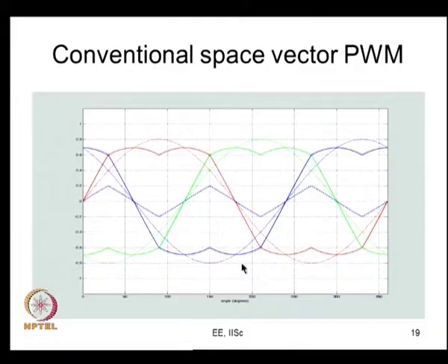So, this is conventional space vector PWM. Here in third harmonic injection, you are with sine triangle PWM and all that, the 0 vector time is there, you apply both the 0 states, and it may not be for equal duration. In conventional space vector PWM, you are adding this kind of a common mode. It is not a third frequency sinusoid, but it looks like a triangular carrier, but it is not triangle, it is actually half of this sinusoid. This is half of this sinusoid, and this is half of this sinusoid, and what goes here is half of this sinusoid.